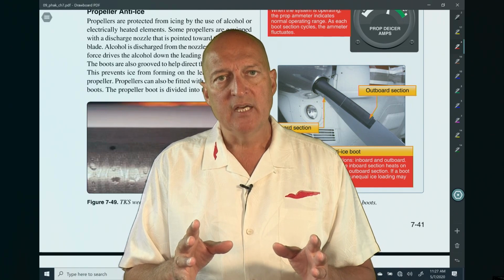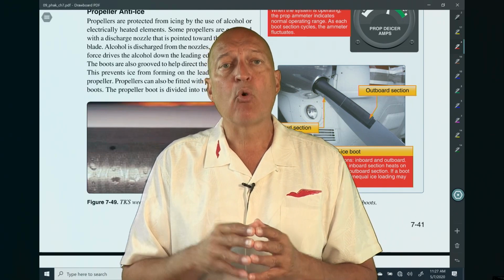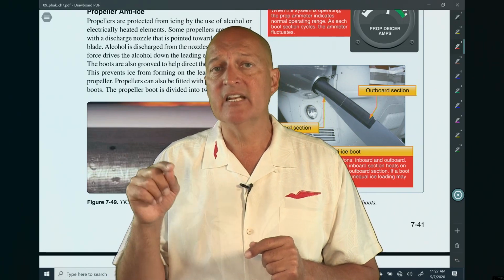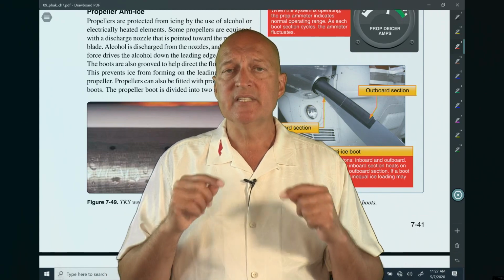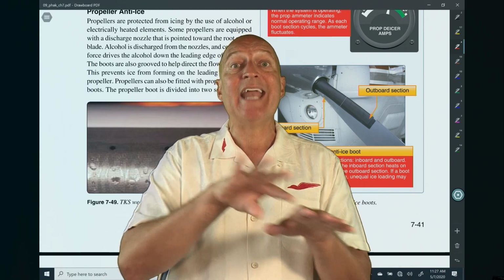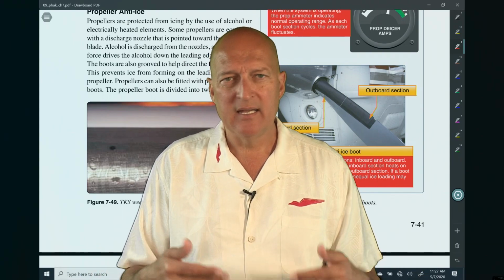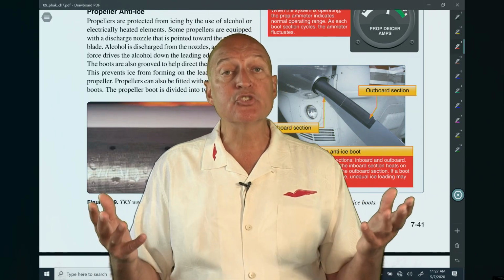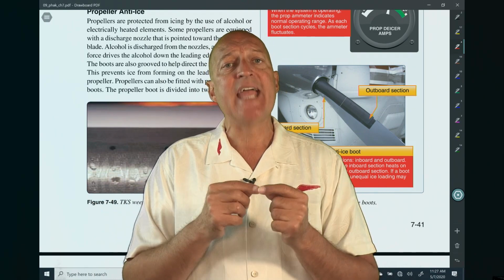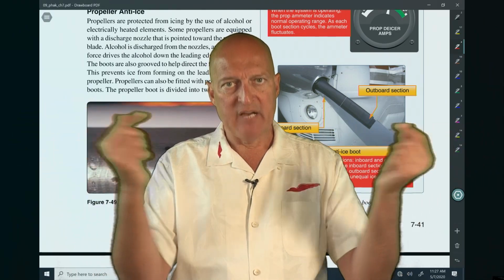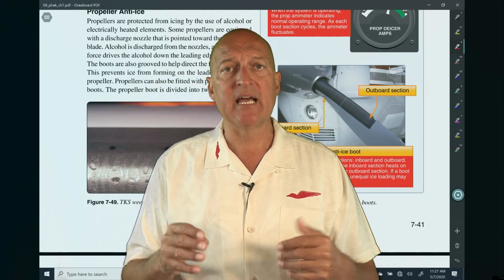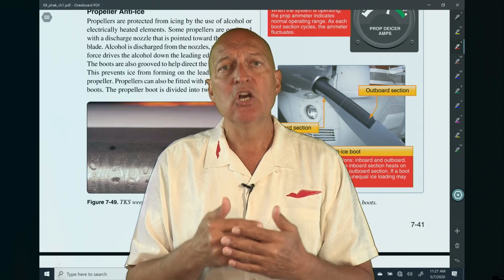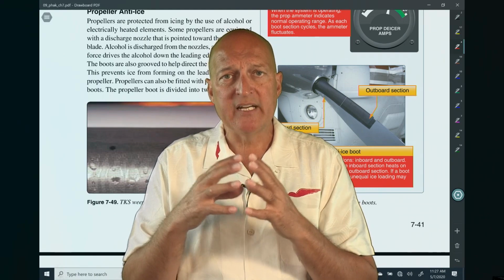There are other systems that are certified for inadvertent ice encounters. So if you fly into an area of icing inadvertently, but you didn't mean to, sometimes these systems can give you the opportunity to get out of that area without any detrimental ice formation on that airplane. Passenger jets, big airplanes with jet engines, can actually heat the leading edges of the wings, horizontal stabilizers, vertical stabilizers, and other components with the bypass air generated from all of the heat that's created in those jet engines.